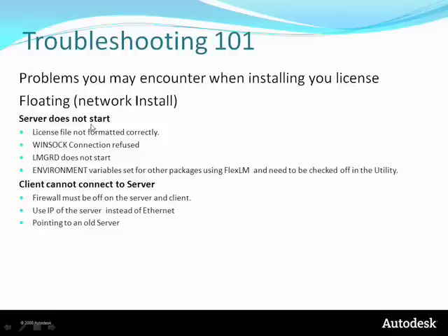If your server is not starting, what could be happening is the license file is not formatted correctly. You could get a WinSock connection refused error when you're doing a perform status inquiry. LMGRD does not start. That's one of the errors that you can get. You could also have some environment variables set for other packages, and I'm going to show you how to check that or disable it. On the client to server side, you could have a firewall on.